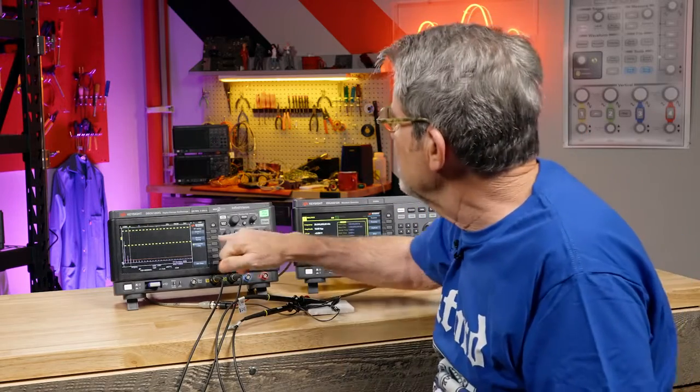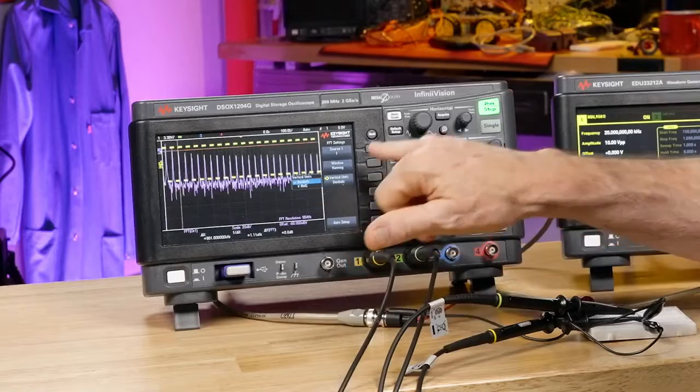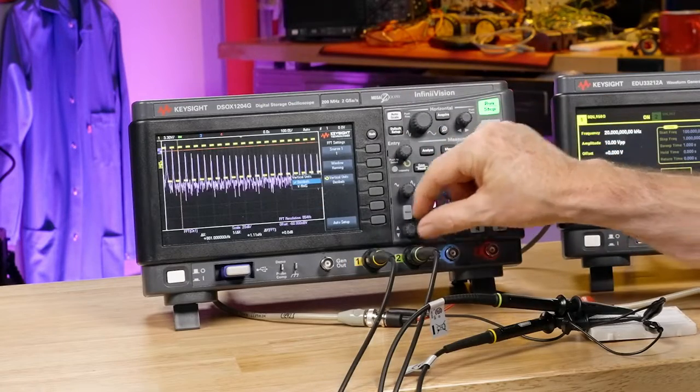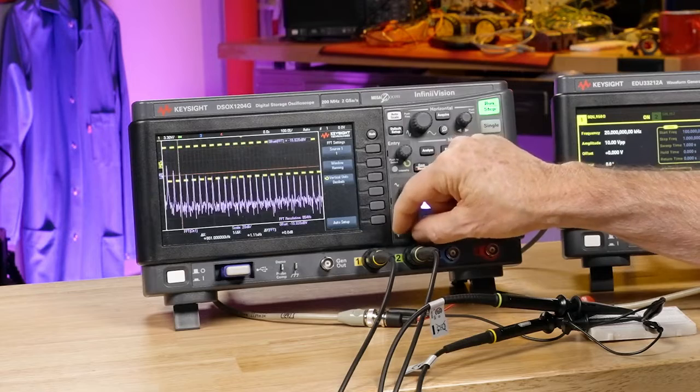But in absolute voltage, you can see the higher harmonics visually are very suppressed. The advantage of the logarithmic scaling, which is pretty typical for frequency domain measurements, is that it visually expands the harmonics that have lower amplitudes. So let's go back to dB volts. Let me get this repositioned again.